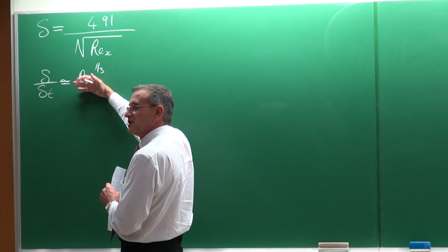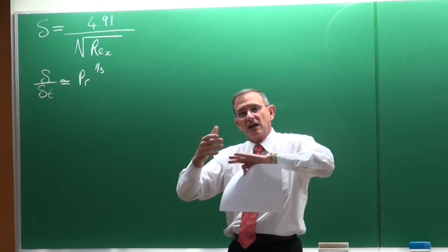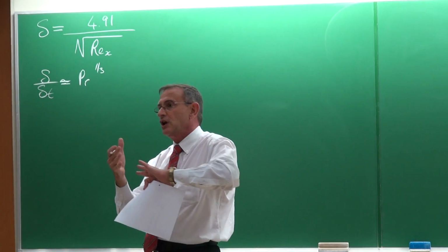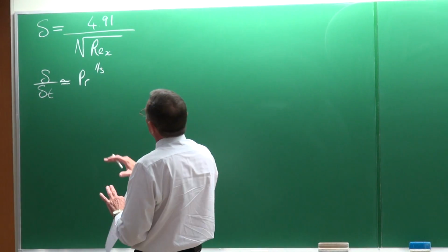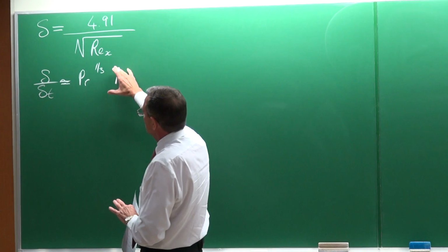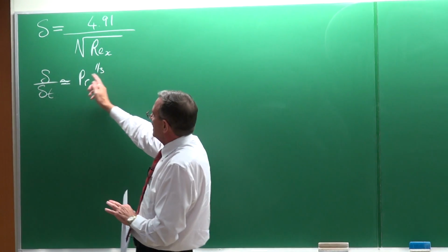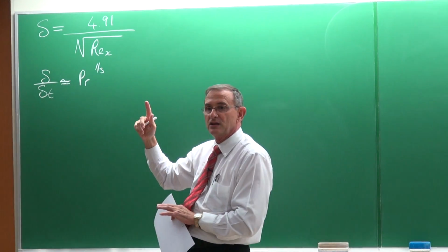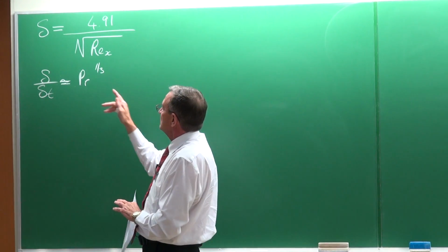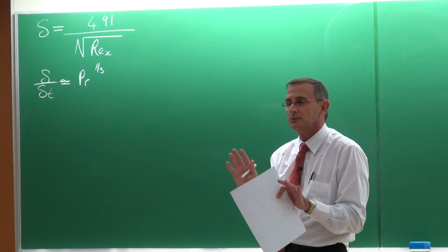We wanted to do the same with the heat transfer. Again, there are lots of similarities between the fluid mechanics and the heat transfer, but the most important result from the previous work is that the boundary layer thickness divided by the thermal boundary layer thickness is always approximately the Prandtl number to the power one third.